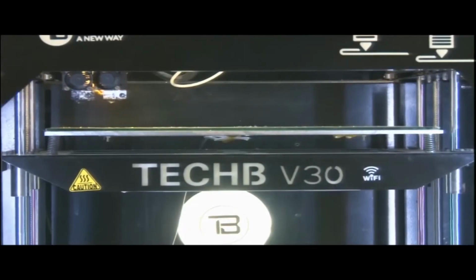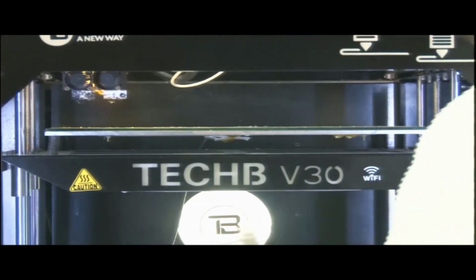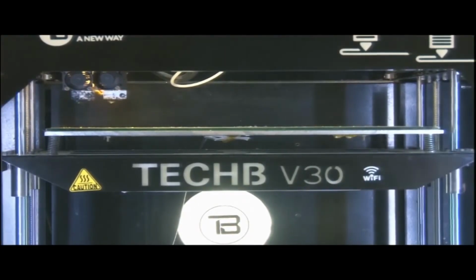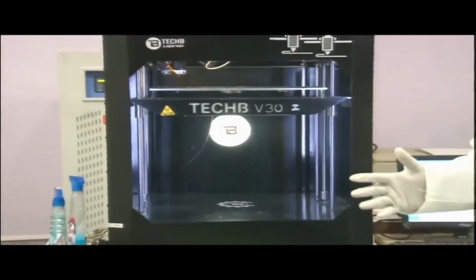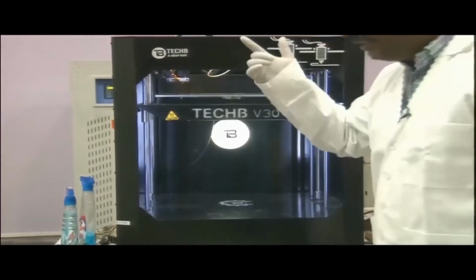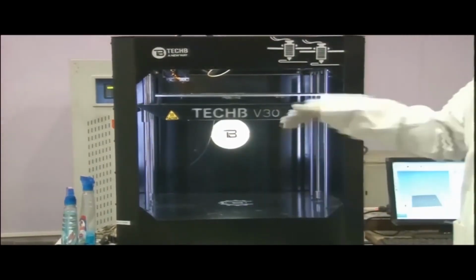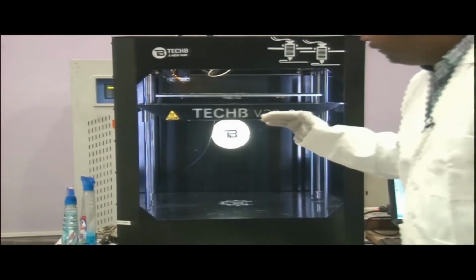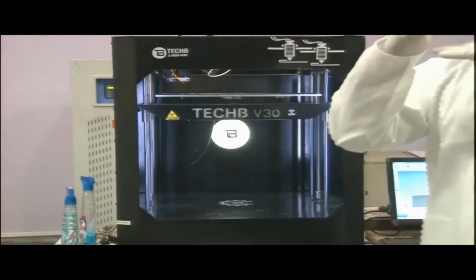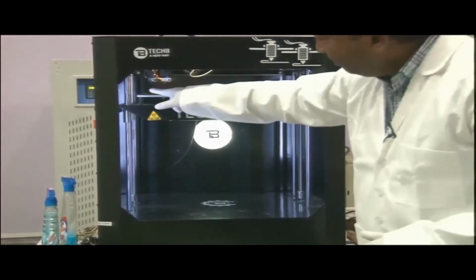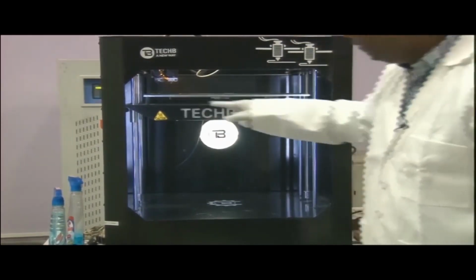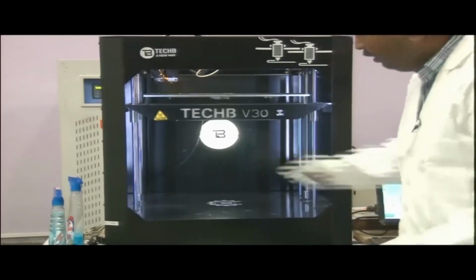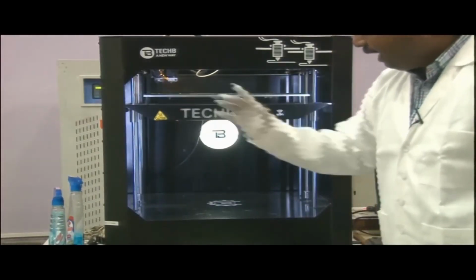In this software, we can set the layer thickness in slicing to 0.1, 0.15 and 0.2, the 3 levels here. Whenever we change this layer height parameter, we need to maintain the gap as well. So let me say I have fixed 0.15 from the top of the bed to the tip of the nozzle. We need to set this gap and lock the limit switch.